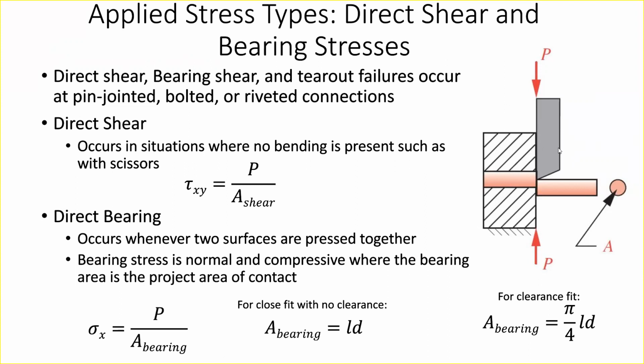So the reason for that is when I apply the load on this part, first of all, what I'm doing is I'm generating a shear on the surface. So the force is acting in plane of the cross section. So I'm generating not a torsional shear, but a vertical shear in this case. So you can imagine the loads or the pressures distributed across this face pointing upwards. So that's the first part of the loading. But if you only support it on one side like this, you also get a slight amount of moment loading.